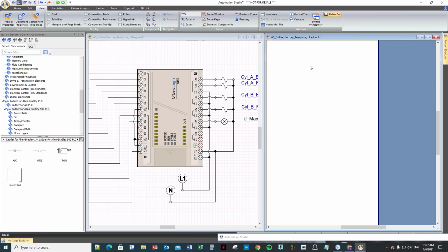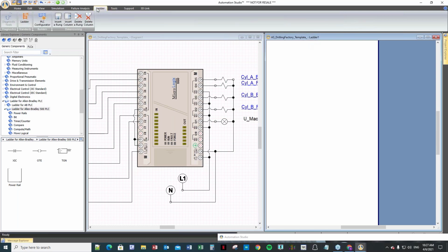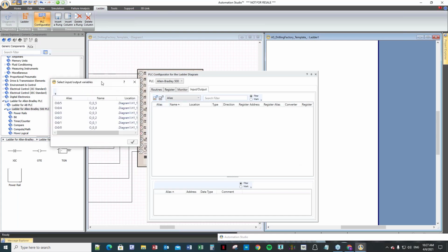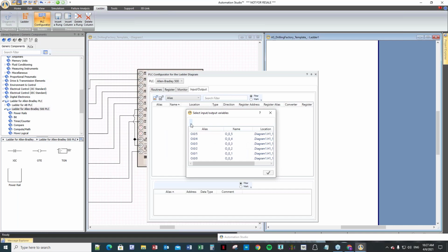to 9. So what I'll need to do, I go on the ladder sheet, and then ladder, and I'll add my inputs. So here I'm going to start with, let's say, my inputs. And then I'm having from 2 to 9. So I can just double click.